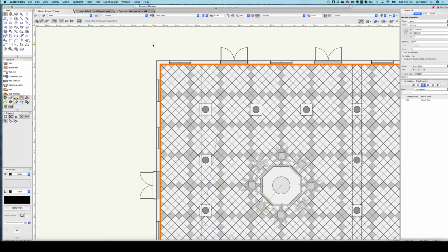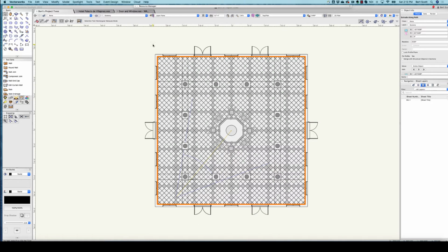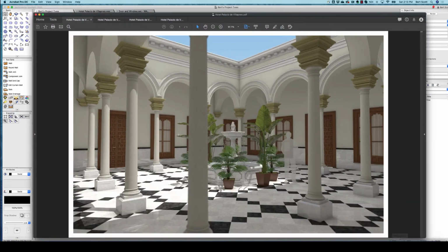We need to do a couple things. We need to separate this into the chair rail, which is the black marble, and the rest of it, which is the gray marble. And we also need to cut some holes in it because of the doors and windows. So what we're going to do is the same thing we did in the previous room project, where we're going to cut the door, we're going to cut all the holes, and then we're going to duplicate this and pull it apart to put it into the two different parts so that we don't have to cut all of the holes twice.